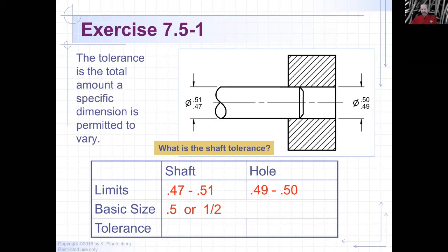And that's called a force fit. So if you're attaching a shaft maybe to a hammer head, right? The shaft needs to be really tight. So you may force it in, and that's called a force fit. And some of the older hammers, if you look at them, have a wooden handle and a metal head. They would force fit the shaft into it, and then they would plunge something in from the top to spread out and cause some more stress and tension so that that head wouldn't fall off.